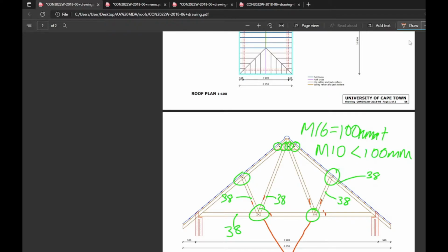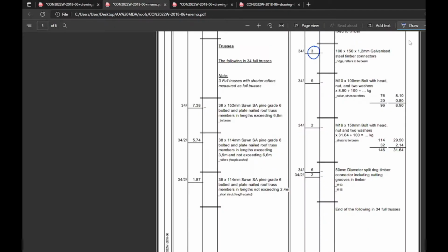3 by 38. Okay, and the rule is you're going to take the thicknesses and 2 times the bolt's diameter. So since this is already 38, and the total is over 100, we'll say this is an M16, okay? Because it's over 100. So we're going 2 times 16 instantly. 2 times the bolt diameter, and that will give you what's going on here.